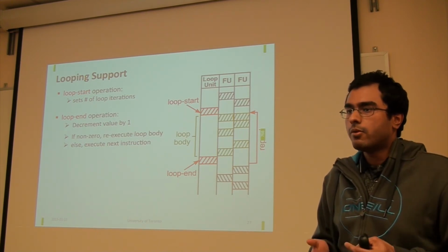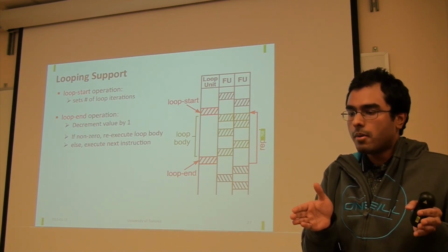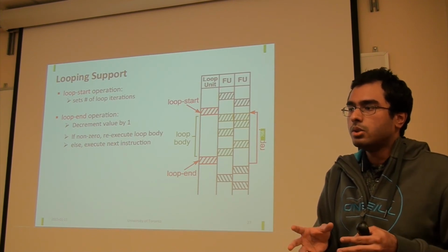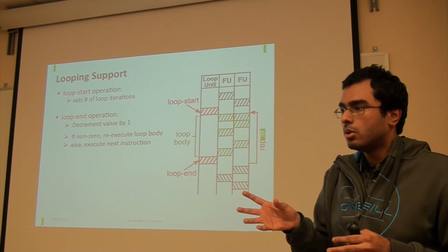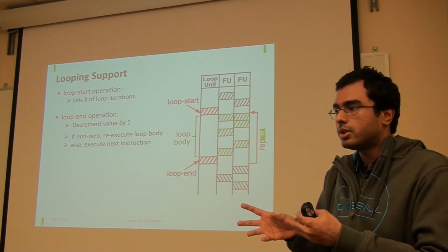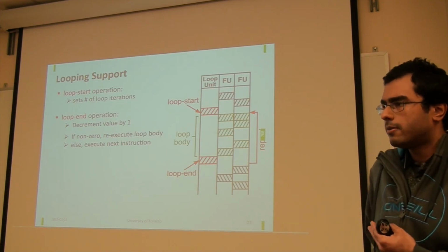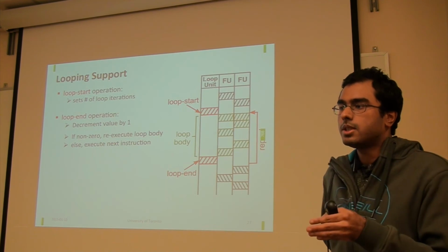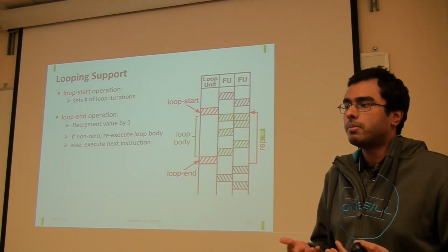Because you might, for example, turn a knob so that you do a bunch of things in a single compute cycle. Or you reduce the number of compute pipelines so that it essentially has to reuse those same resources at different cycles. That's what I've alluded to with the FIR computation, where we performed the same 64-tap FIR computation, but with fewer DSPs. And what do we end up with because of that?